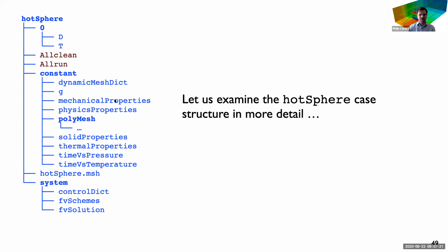Mechanical properties, we'll look at that further. That's where you define the constitutive law. Like I said before, in fluids, the turbulence model is the critical thing, whereas in solids, the mechanical model or the constitutive model is the critical thing. So when we compare it to what happens in real-life physical solids, if our answers don't agree, apart from the numerical schemes, it's mostly because we can't describe the definition of stress as well as we would like.